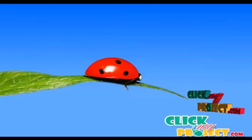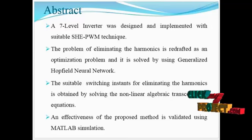Inverters. The circuits which convert a DC signal into an AC signal are called inverters. Various types of inverters are available: single-phase single-level inverter, multi-level inverter, and multi-phase multi-level inverter. But the multi-level inverter is one of the most recent advances in power electronics. The desired output voltage waveform is synthesized from several DC sources.